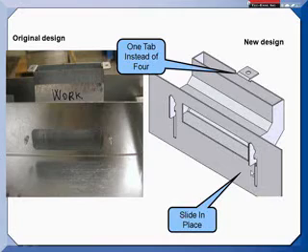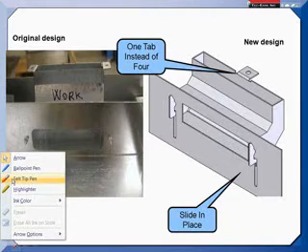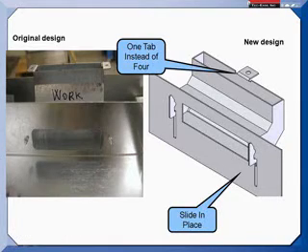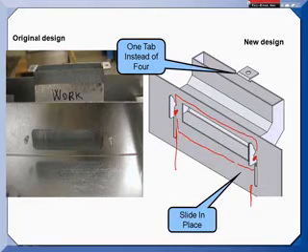Maybe I should not be so lazy and get my pen out here and mark these for you. So on the back surface we're mounting, if you had your X-ray vision on, you could see that. And then we're hitting here and here. And then this distance from there to there is fairly tightly controlled. And so that's locating the part left-right. That became essentially our tertiary datum feature for those tabs.